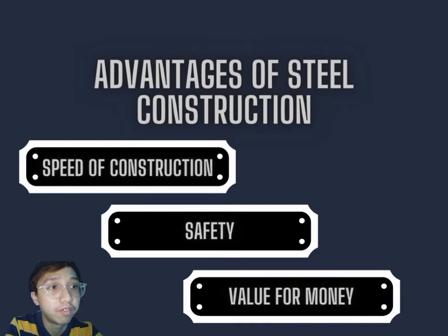The majority of structural steelwork is prefabricated with very little site work required other than assembly via bolted connections. This leads to fast construction times and, with attention to staged delivery, decongested construction sites, which makes it ideal for congested CBD building projects on small sites. With up to 70% labor reduction possible using a steel solution compared to alternatives, fewer people equals a safer construction site.